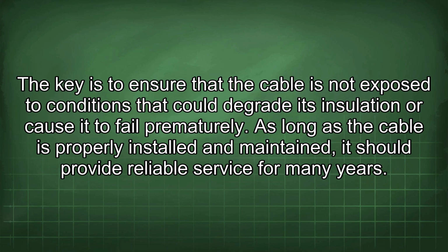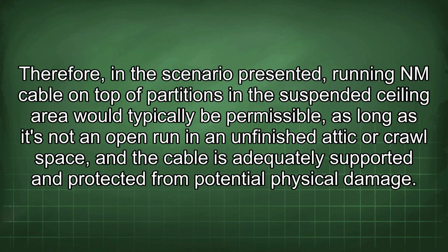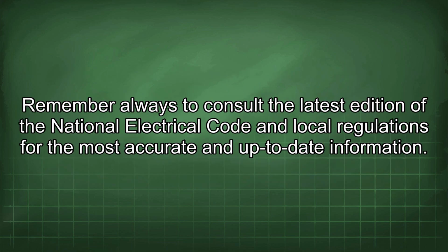Therefore, in the scenario presented, running NM cable on top of partitions in a suspended ceiling area would typically be permissible as long as it's not an open run in an unfinished attic or crawl space and the cable is adequately supported and protected from potential physical damage. Remember always to consult the latest edition of the National Electrical Code and local regulations for the most accurate and up-to-date information.